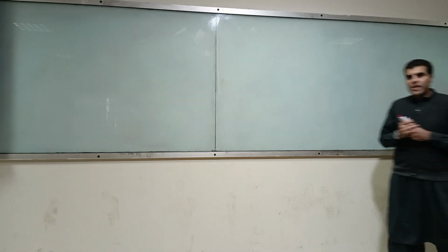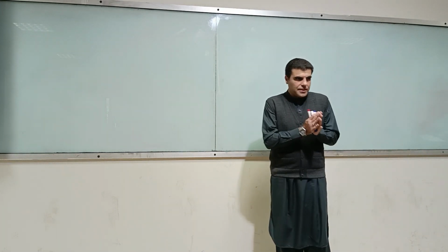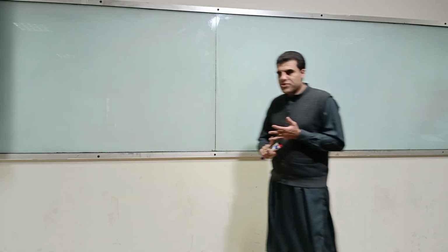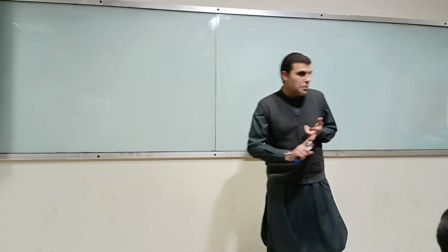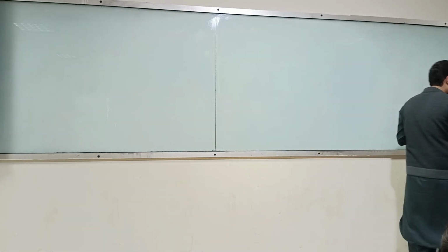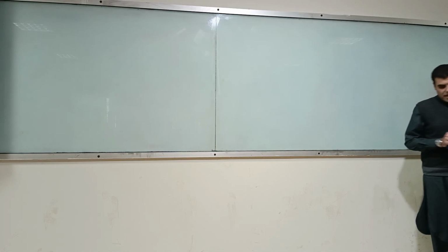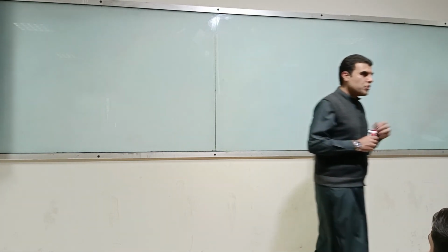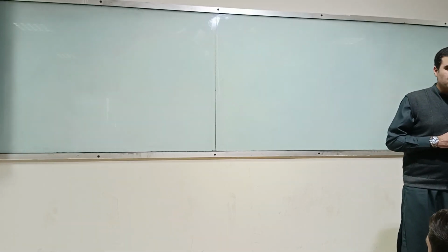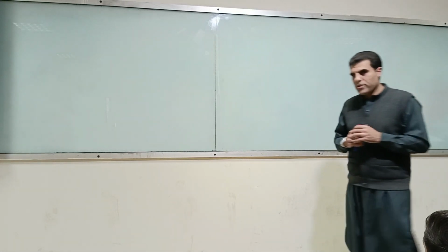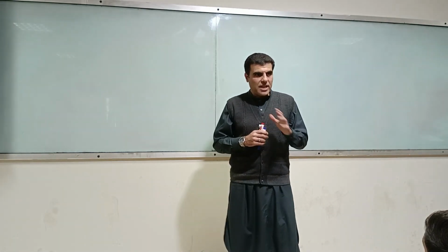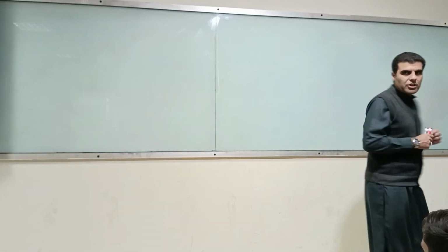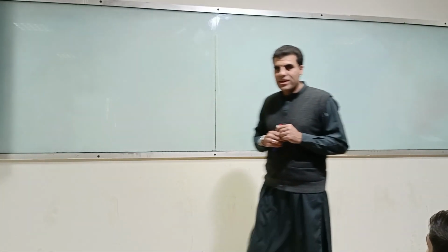The first starting point. Okay, can I have your attention, please? Okay, so we discussed what determinate structures were, indeterminate structures, and then how stability is relevant to our determinacy and indeterminacy. Okay, the determinate structures we said are those structures in which you have got number of available equilibrium equations equal to number of unknowns. Okay. So, number of available equations are the equilibrium equation depending whether you have a 2D structure or a 3D structure.